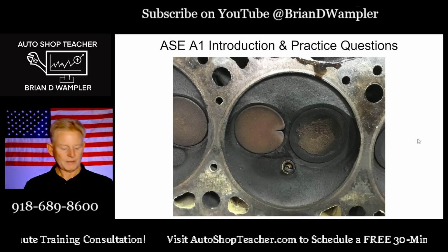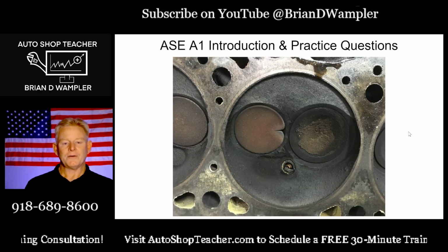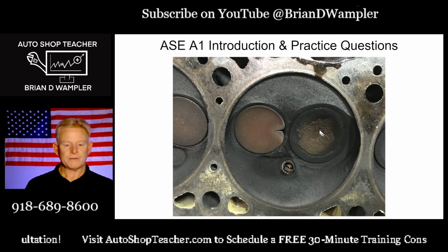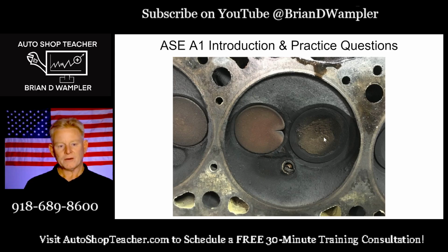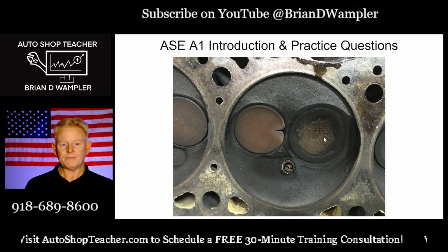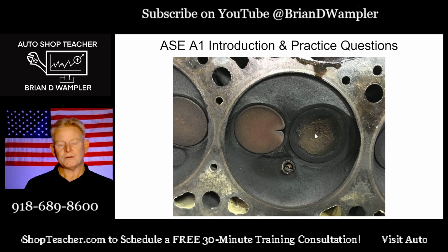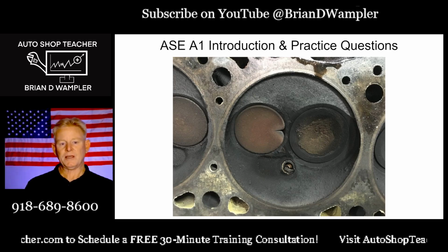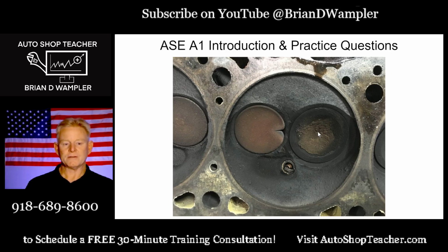Okay, so here's an example of a very well burnt exhaust valve. Generally, the intake valves, especially in just a 2-valve system cylinder head like this, the intake valve is going to be larger, because remember, it's bringing in air and fuel. Then the exhaust valve is typically, but not always, a little bit smaller, because it's just exhausting those inert, meaning spent gases and whatever's remaining in the cylinder.